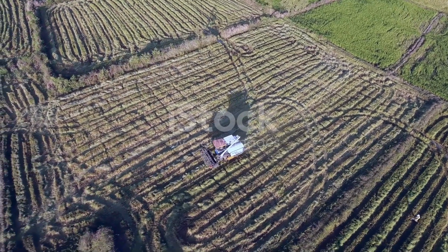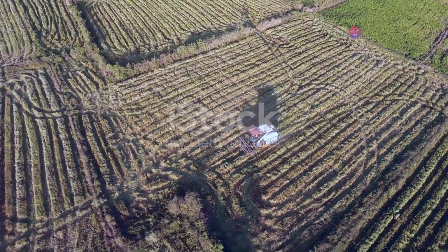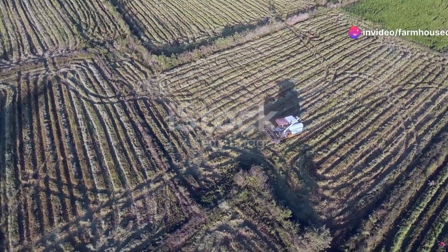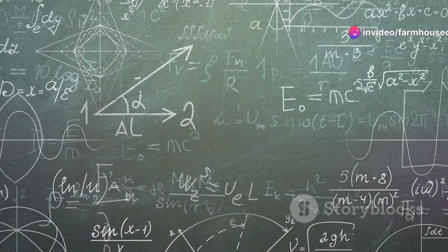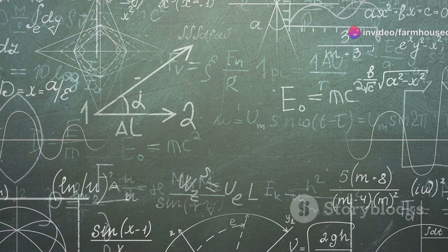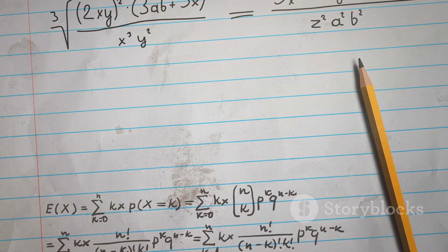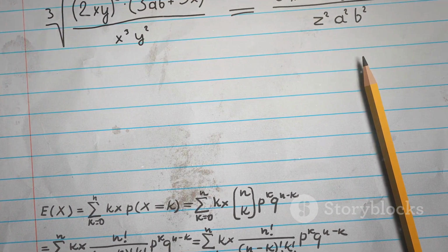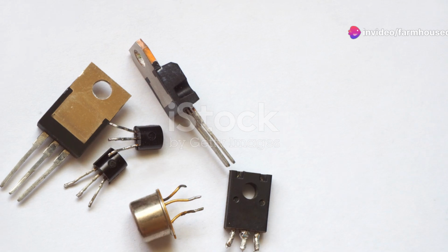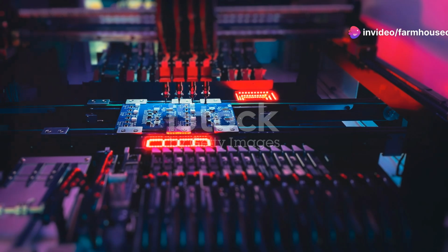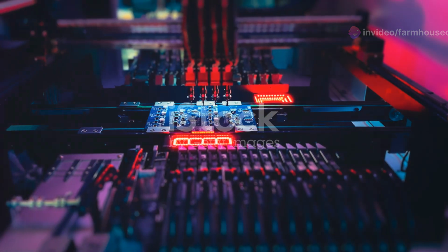After obtaining the product terms for each group, we combine them using the OR operation, symbolized by a plus sign. This combination gives us the sum of products, or SOP form of the simplified Boolean expression. The resulting expression will be simpler than the original. It will have fewer terms and variables. This simplification is the primary advantage of using K-maps. It translates directly to a more efficient digital circuit implementation.